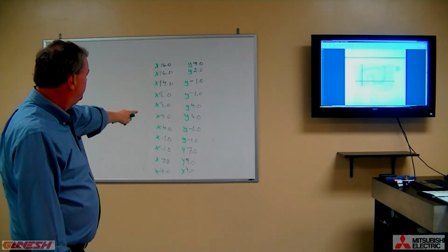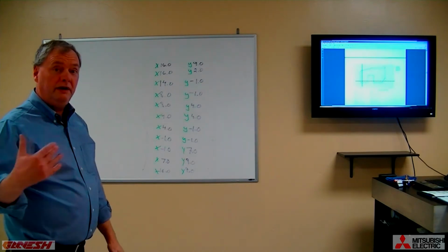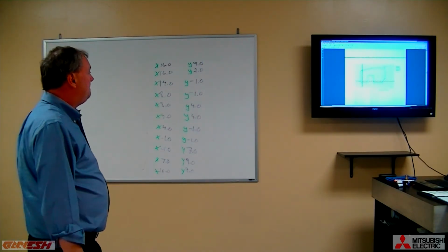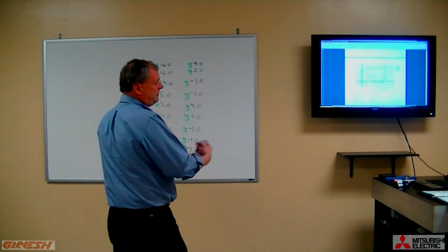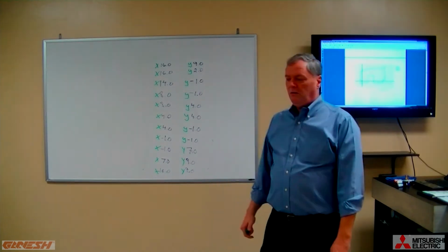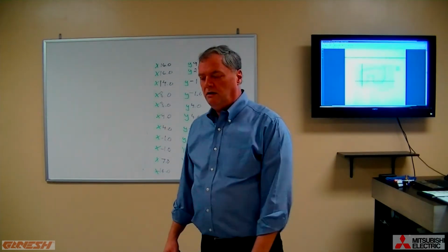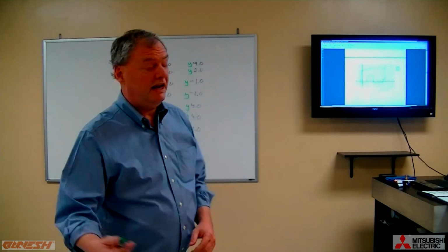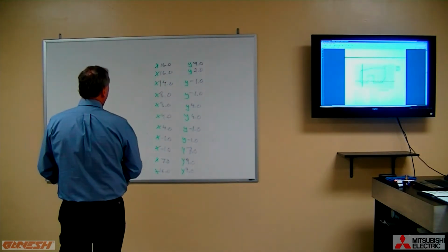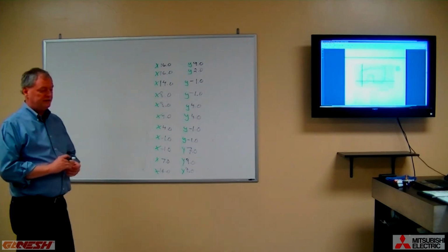Typing this into an NC control will give you valid movement, but you have to qualify it. There's many things that come into play. For example, we need to tell the NC control what kind of units these are. Are they inches or are they millimeters? So the first thing we're going to talk about are what we call preparatory functions.